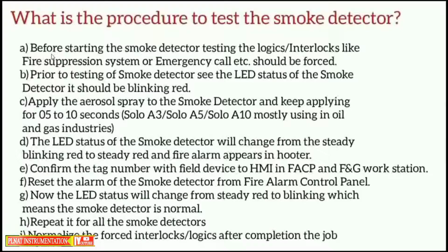What is the procedure to test the smoke detector? Before starting the smoke detector testing, the logics interlocks like fire suppression system or emergency call should be forced. Prior to testing of smoke detector, see the LED status of the smoke detector. It should be blinking red. Apply the aerosol spray to the smoke detector and keep applying for 5 to 10 seconds.